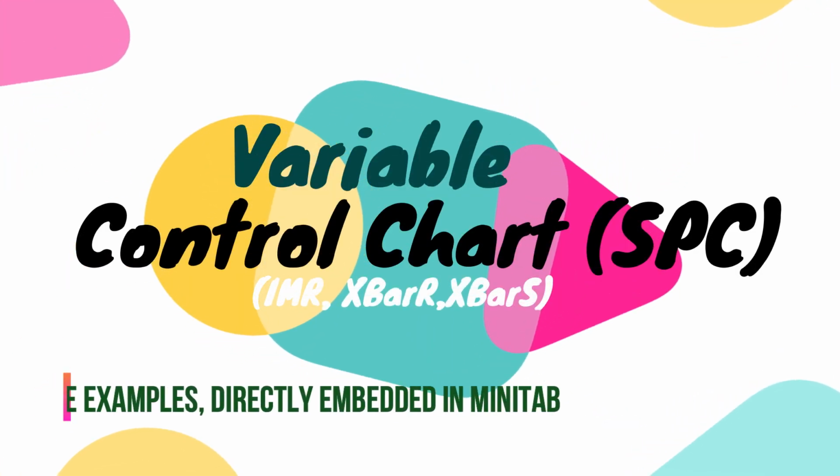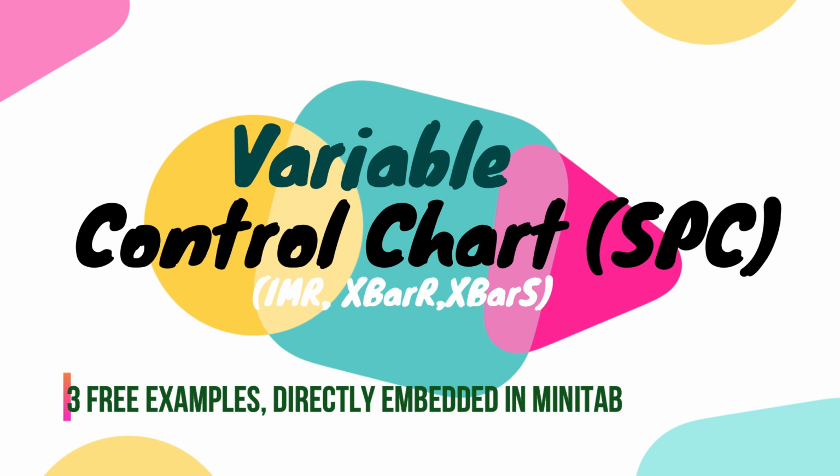Today we are going to discuss a wonderful topic called SPC. In SPC we are going to discuss control charts, variable control charts. There are three variable control charts we have, right? So IMR, XBarR chart, XBarS chart, and we are going to see them all together.